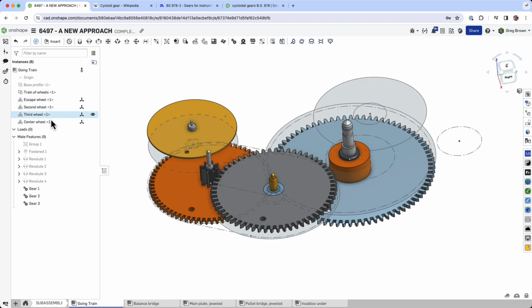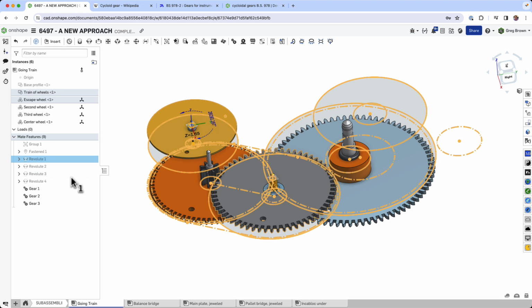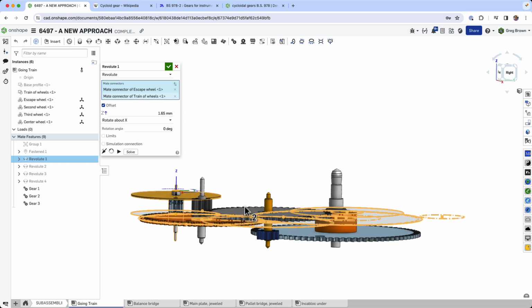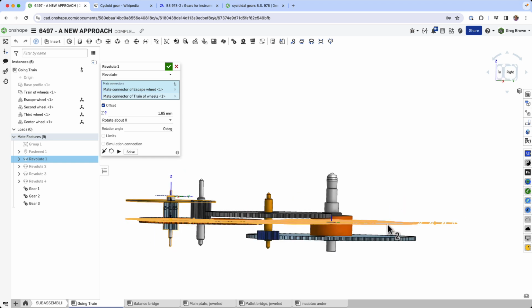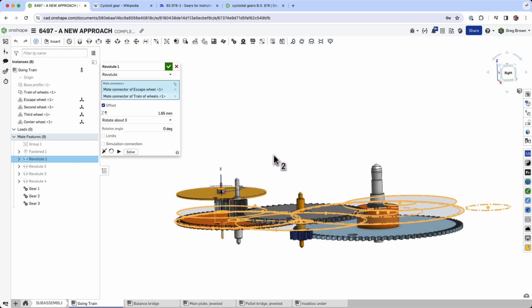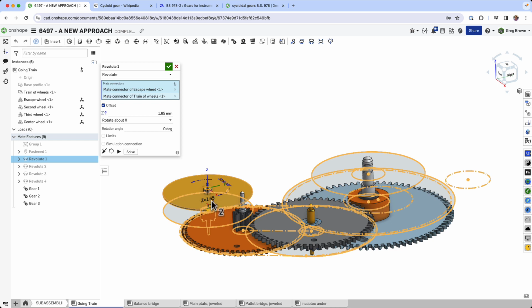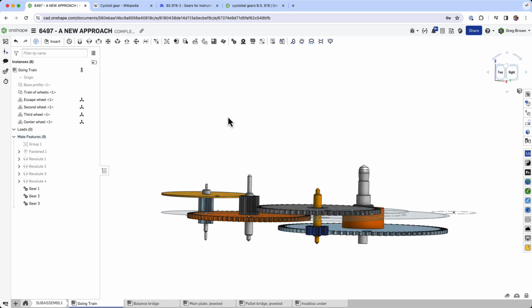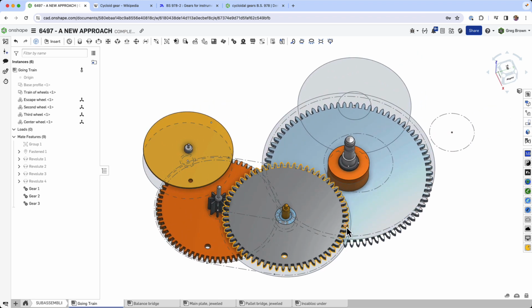All right, so those go in, and I've got revolutes. Now these revolutes contain an offset from this original. You can see the layout sketch is really at the origin, at the Z0 origin, but this wheel has its bearing surface 1.65 millimeters up from that. Now again, this is being driven by a variable, so it's not going to ever be wrong. The same with these other ones. Variable, top-down driven, layout driven, with composite parts really has been the answer here to create a really efficient, compact, easy to diagnose